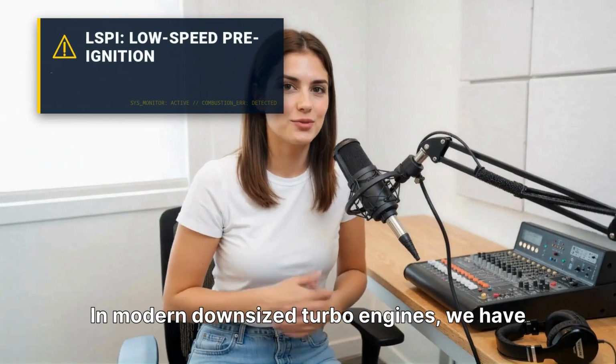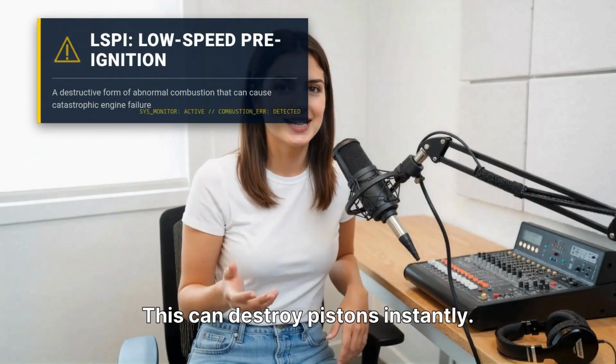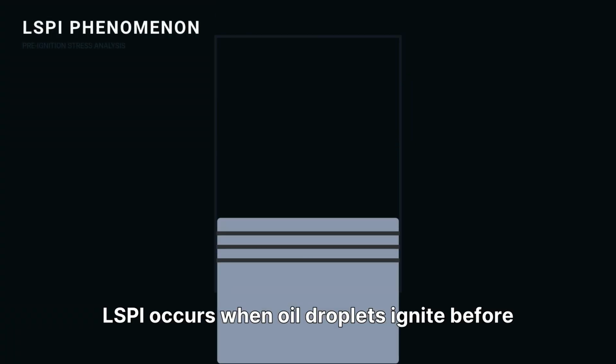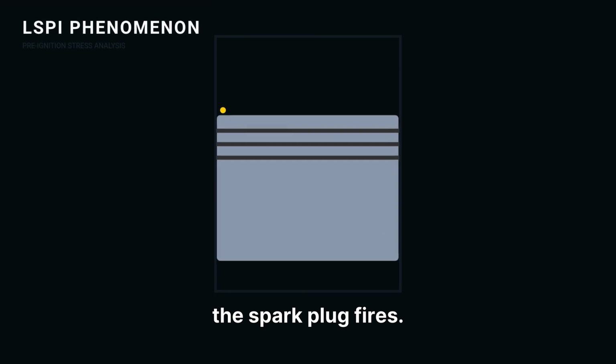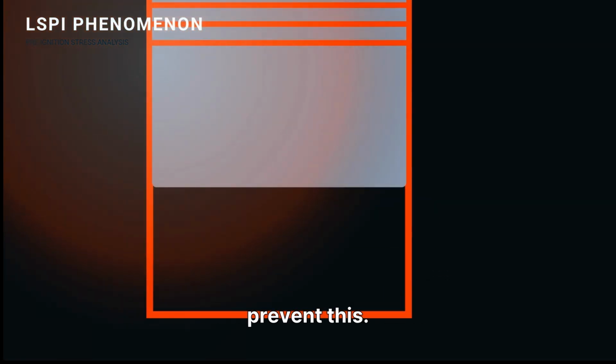In modern downsized turbo engines, we have a new challenge: low-speed pre-ignition. This can destroy pistons instantly. LSPI occurs when oil droplets ignite before the spark plug fires. Specialized synthetic additive packages are required to prevent this.